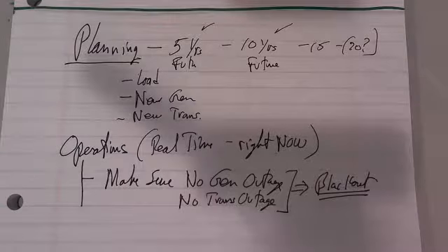But a blackout occurs typically, here's a typical situation. You'll have a transmission outage, and you'll have some overloads and some low voltage. And then, if you haven't planned it right, the first outage causes the system to overload someplace else, and suddenly that system has a low voltage and it opens some other equipment, and you begin to have what's called a cascading outage.